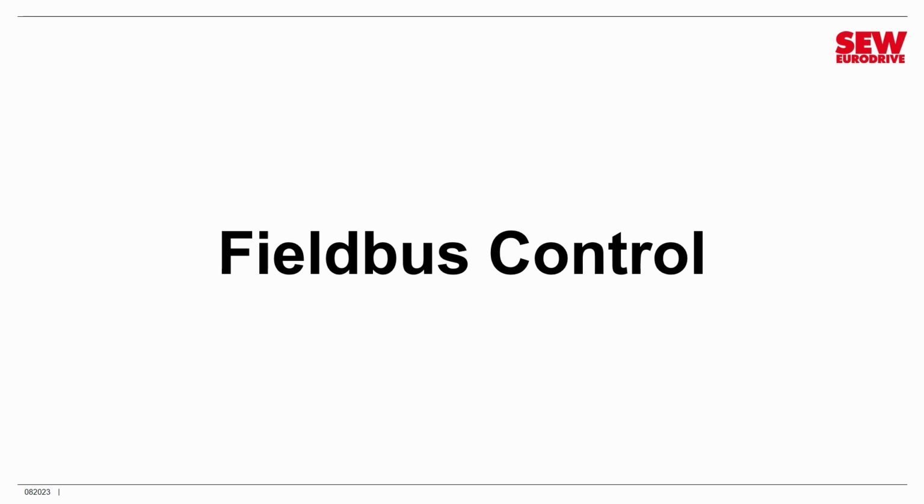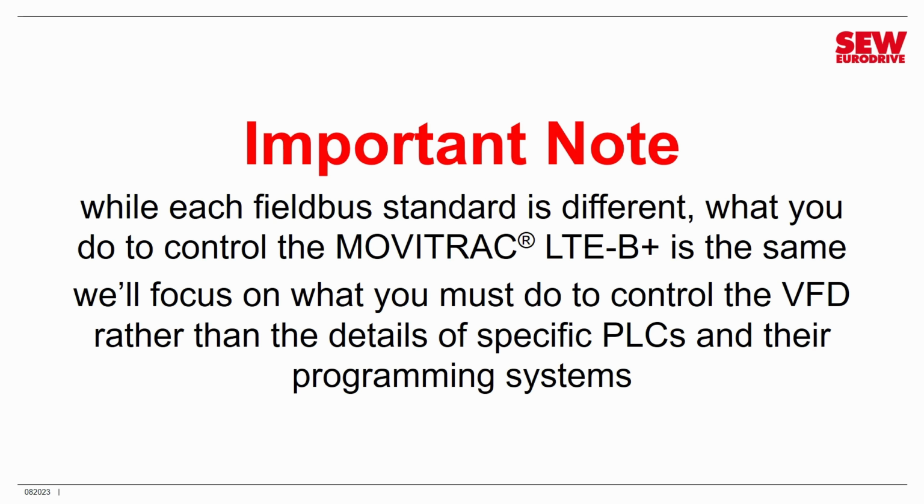Now, I want to make a very important point on this. There are many different PLCs, many different programming systems out there, and obviously we can't get stuck in the weeds trying to deal with all the different possibilities. So, here's how we're going to approach it. Each field bus standard is different, but what you do to control the MOVITRAC LTE-B Plus over it is the same. The information you have to send from your PLC or other industrial controller to the MOVITRAC over the field bus is the same across all platforms.